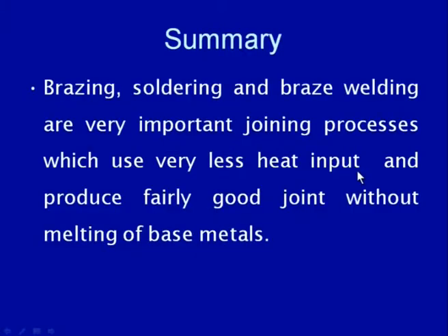Another key feature of these three processes is that very little heat input is used for development of the weld joint, and the joint has fairly good strength, but not for conditions that are high in temperature, or where very severe loads can act on the joints. But under conditions where the load is fair and not on the higher side, these joints can be easily and effectively used. And in these three processes, the base material is not brought to the molten state for development of the weld joint.